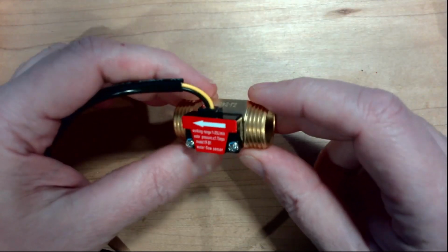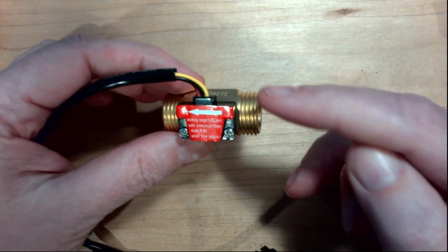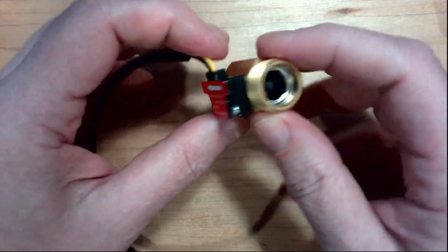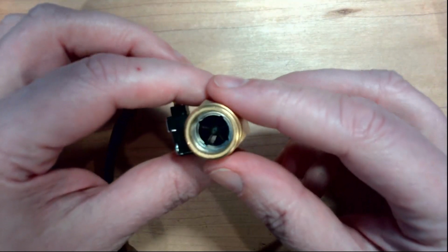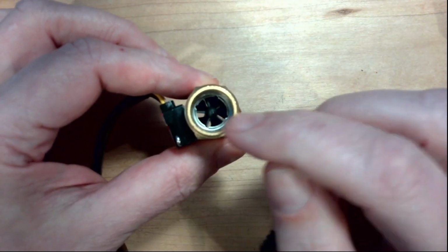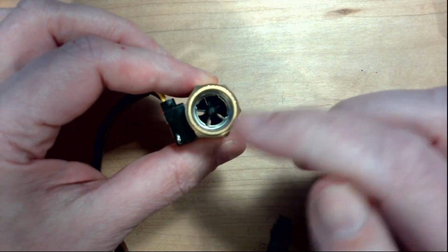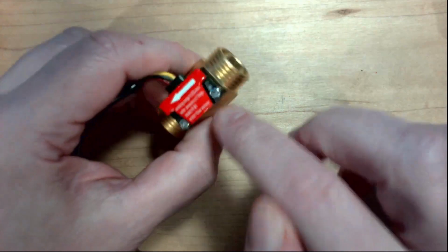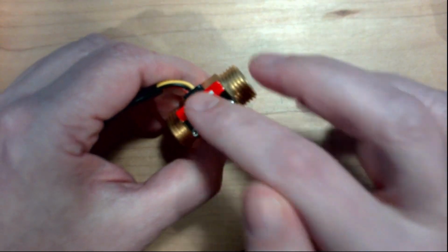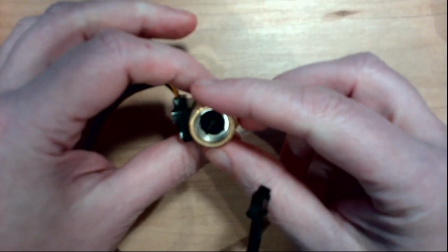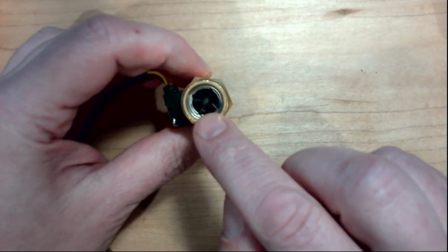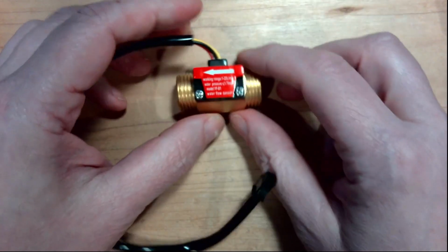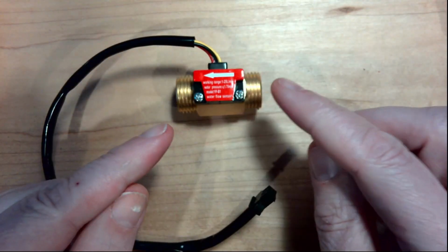This sensor has something in it that rotates, and that rotation turns into pulses, and those pulses can be changed into a flow rate. This style here, you can kind of see in there, it's got basically like a propeller or a turbine that rotates, and then that rotation basically has magnets that pass a sensor here for a Hall effect, and that turns into those pulses. There are other styles that have a paddle wheel that rotates this direction that go past, but they do the same thing. In fact, let's go look at a couple more.